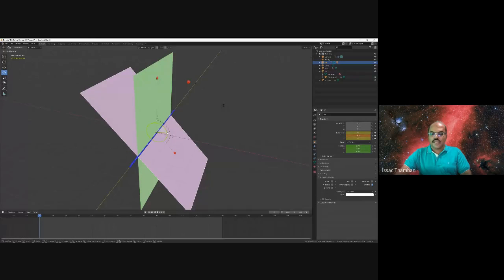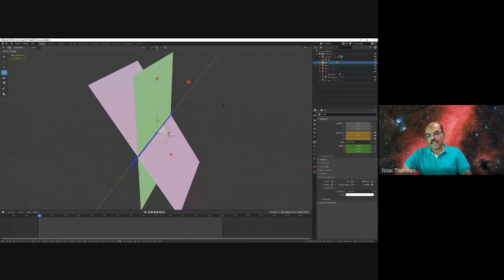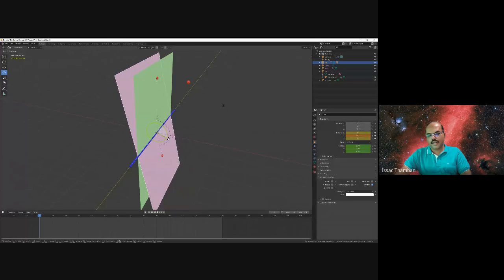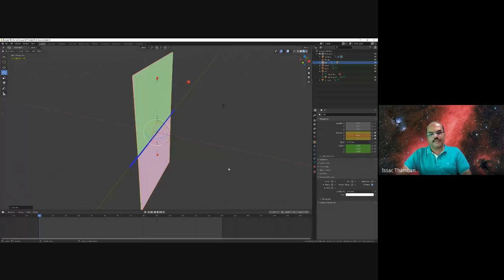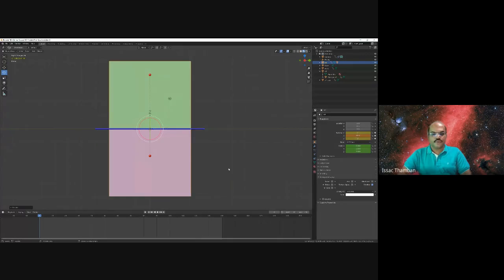If you are tilting the horizontal plane like this, then what will happen to the projection? The projection will also follow the plane. So, I am tilting again and again, and finally it will overlap with the vertical plane. And after that, I am looking from the front. You will get a view, isn't it? Here, this is our elevation and this is our plan.